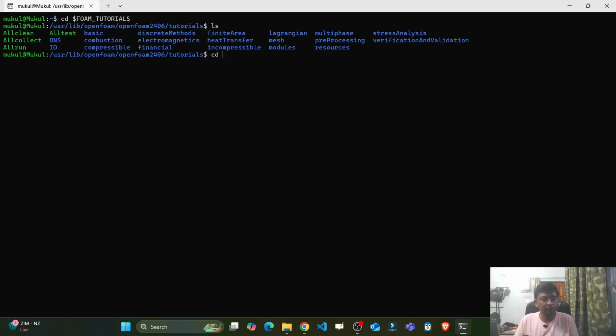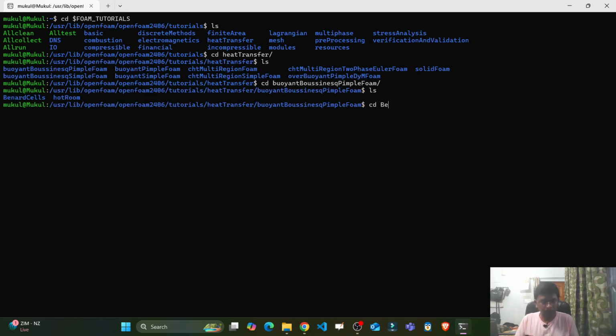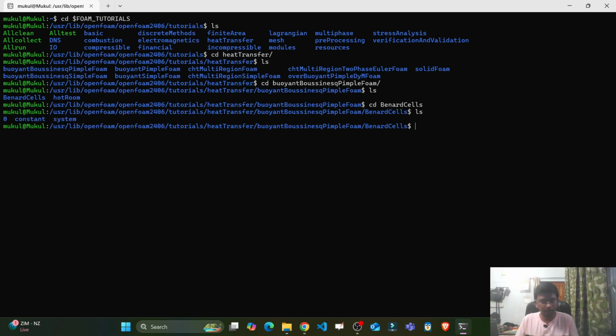Okay, so we will open foam tutorials, then we will go to heat transfer, then we will go to buoyant Boussinesq pimple foam. You can see that Bénard cells are here. Okay, so I have already copied the whole heat transfer tutorial to my home directory.